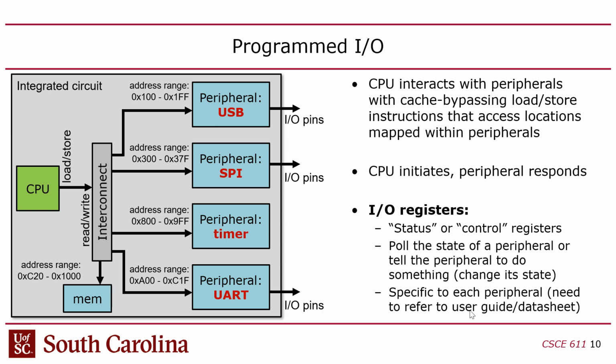And all the embedded systems have adopted that. It was a standard that ARM came up with about 30 years ago. And for whatever reason, it just emerged as the standard. IBM had one called CoreConnect that Altera FPGAs and Xilinx FPGAs used to use, but they got rid of it in favor of AXI. And there's another one on Intel FPGAs called Avalon, which you can still use, but they're even replacing that with AXI, right? So this is basically an on-chip network.